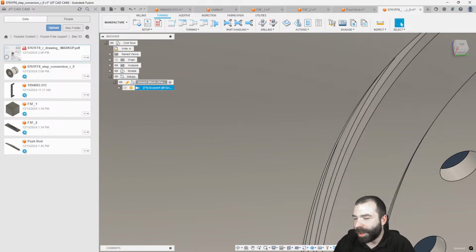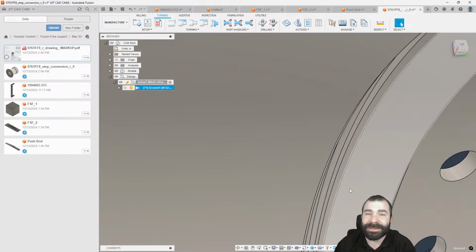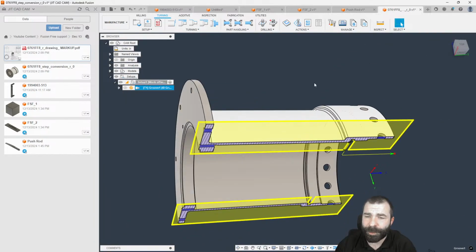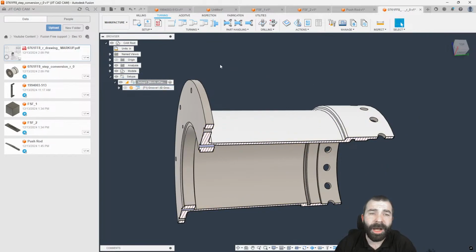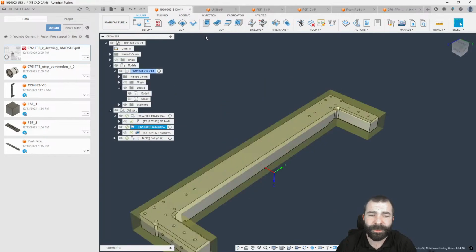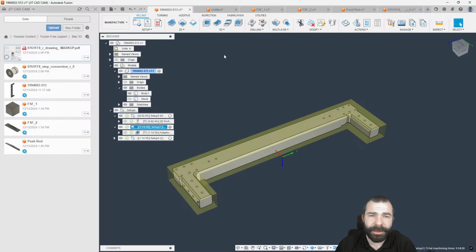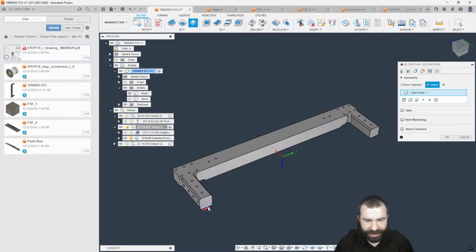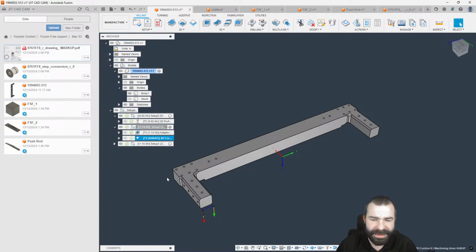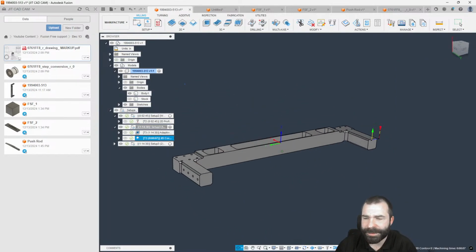How would you have a tool automatically check for breakage and wear after running a certain amount of parts? Well, so if you wanted something based on a macro on your M30s, there's a couple ways to do it. We've modified post processors for things like that. The easiest way, if you guys have never seen this inside of Fusion, let me get back to a little different part here. As you can see, I have my part here. Let's say we were doing our 2D contour, and let's just put one right at the end, right? Let's just make this as easy as can be. Obviously, our part's upside down, right?